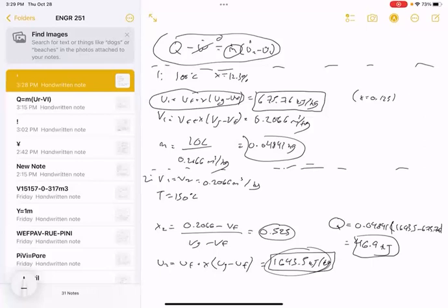So whenever you look at a change of state, you know that any one of these four things or a combination of them happened. In this case, based on the context of the question, we know there's no work interaction. But because the internal energy increased and there is no other change in kinetic or potential energy, by identifying state 1 and state 2 we can see that it went from 675 to 1643. If there's an increase in energy, that means energy was added to the system. And we know there's no work that can be done to or from the system.